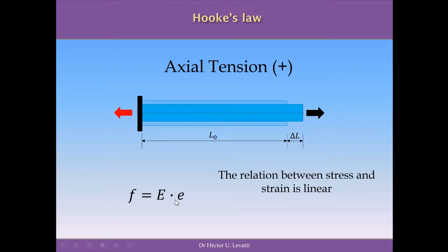So as you see, the relationship between the strains and the stresses is linear because E, the Young modulus, is usually a constant value, and then this equation is a linear equation. So the variation of the stresses regarding the strain will be linear, just multiplied by a constant, which is the Young modulus. And again, the units for the Young modulus are units of stresses.